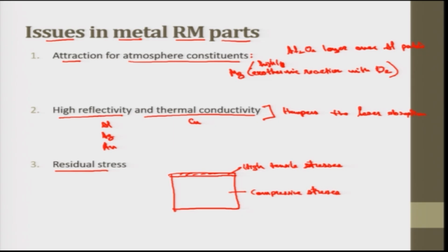Now, here stress gradients also develop in the build direction depending upon the part geometry, height and the connection method to the base plate. So, this quantification of residual stresses is also necessary, and researchers are working on them to mitigate this defect. While deformations due to residual stresses are a general phenomenon, the occurrence of cracks and types of cracks are material dependent. So, residual stresses can also lead to micro cracks, maybe at grain boundaries, then embrittlement; crack initiation sites are there at the high residual stress points. So, this is also to be countered.